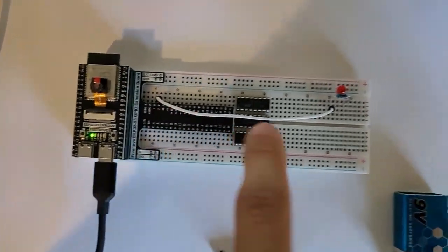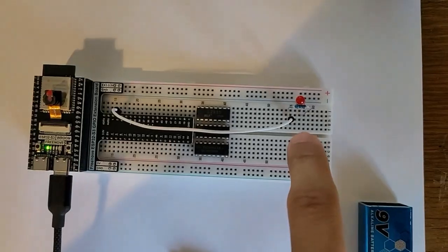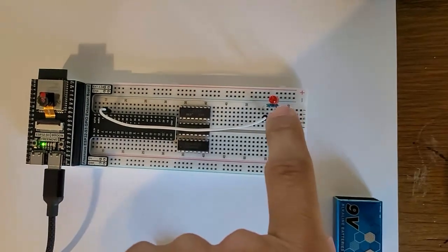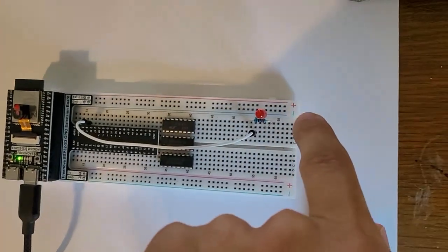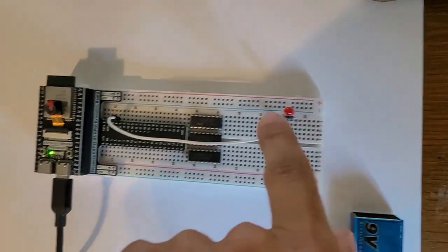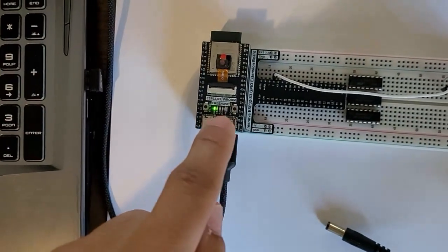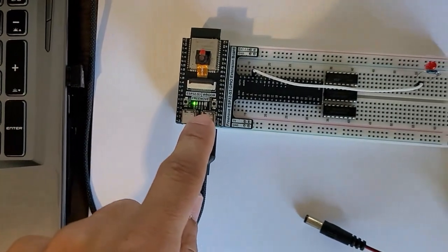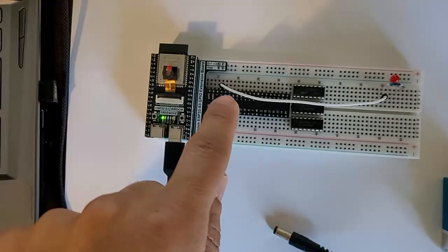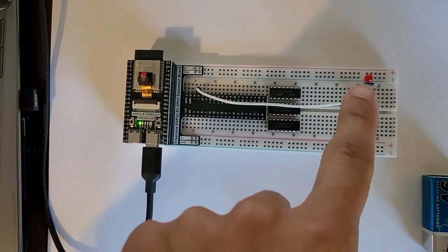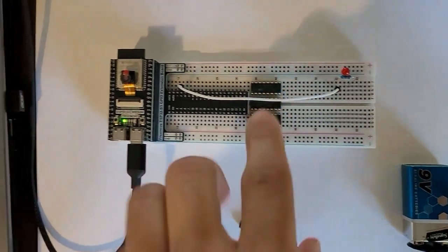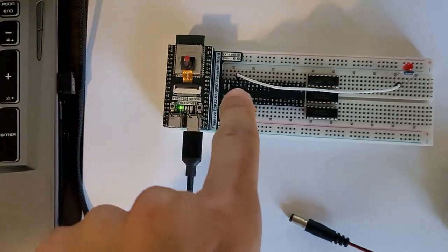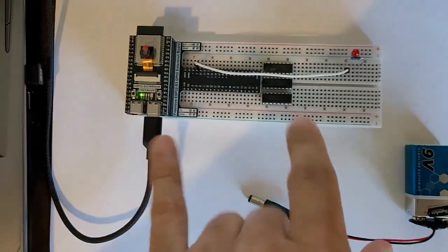Off of pin 2, we have a wire going to a resistor. Then in series, the LED, which is then connected to the ground. The onboard built-in LED currently is programmed to operate in unison with this LED. For parts 2 and 3, I'll be changing this wire to pin 1, so there are different variables.